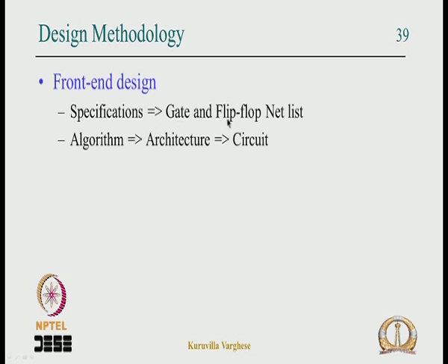So as I said, there is something called front end design, which goes basically from specification to the gate and flip flop level circuit or the netlist, or we can say from algorithm we design an architecture and we go to the logic circuit in terms of the gates and the flip flops, and this is many times called logic synthesis. This step of going from an architecture to the logic level circuit is called logic level synthesis.